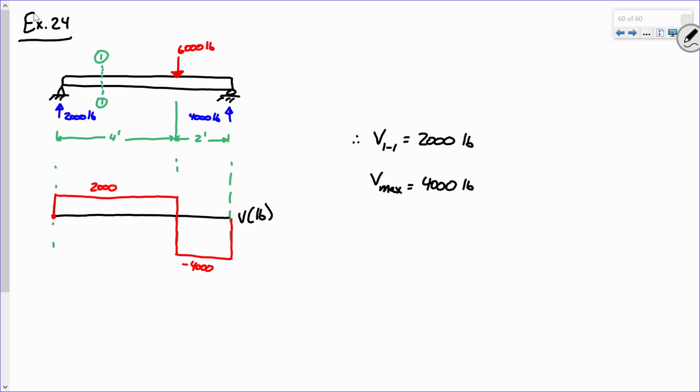Because I'm looking at magnitudes. What is the largest magnitude shear that this section is facing? It's 4,000. By and large, in the world of shear, while we need a correct sign convention to draw our moment diagrams, the direction doesn't really matter for shear. An element largely behaves the same way if I'm shearing it like this or like this. It's still shear. Now the compression versus tension on bending, you need to be a little bit careful with. But all in all, the direction really doesn't matter. Sound good?